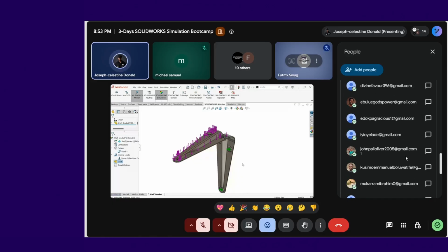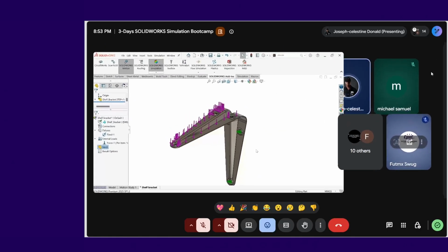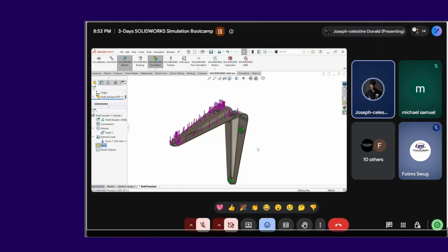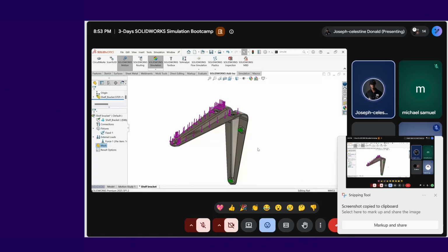When you use a fine mesh, it's split into much smaller parts, so there are many more parts to walk through. You get a much more precise result, but it takes longer to solve. So the real skill isn't using the finest or the coarsest mesh. It's knowing at what point you need your mesh to be fine and at what point you need it to be coarse.